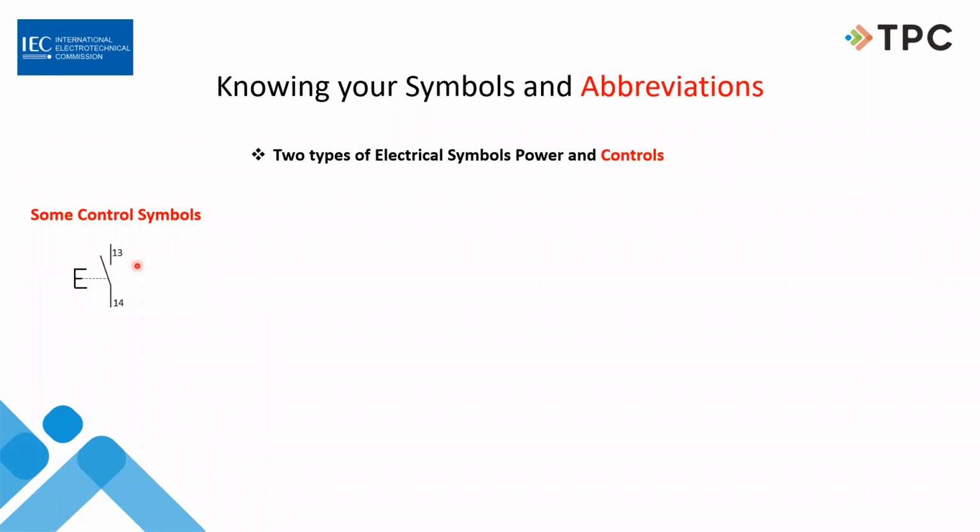We're going to talk about what these numbers mean in a little bit, because they're also telling us that this is normally open, because anything that has a 3 and a 4 means it's normally open. So we've got this normally open push button and it's momentary. When I put this little block over here with a 1 in it, it tells me immediately that this is a push button.